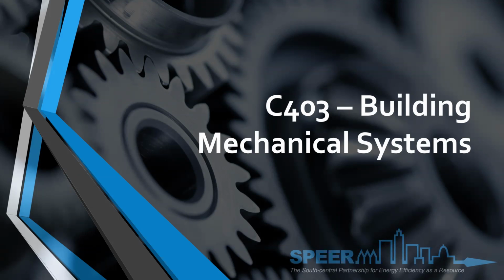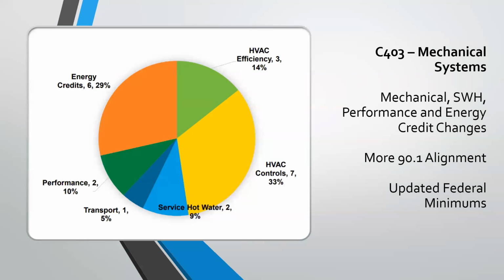The Building Mechanical Systems for Commercial, the C403 chapter of that. With the 2021, we had quite a few changes. The majority of those came from HVAC controls: 21 changes altogether, and 7 of those were HVAC controls. That deals with HVAC monitoring and fault detection monitoring for buildings over 100,000 square feet. Also mechanical, water heating, and performance and energy credits changes.